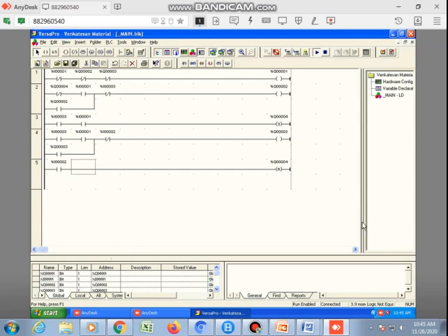So I repeat again, the conveyor will run as long as we are not receiving any product at the proximity sensor. Until the proximity sensor is sensed, or until the robo arm is in stable position, it is not moving either forward or in reverse, and the conveyor will keep on running. So the conveyor will stop and will try to pick the material.